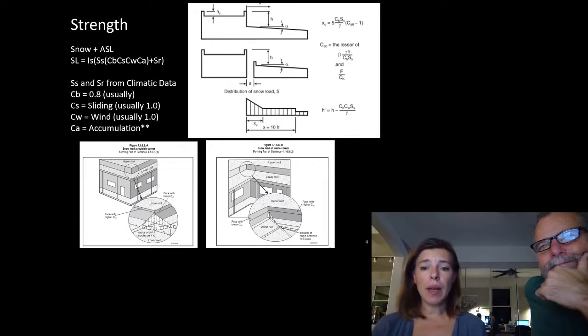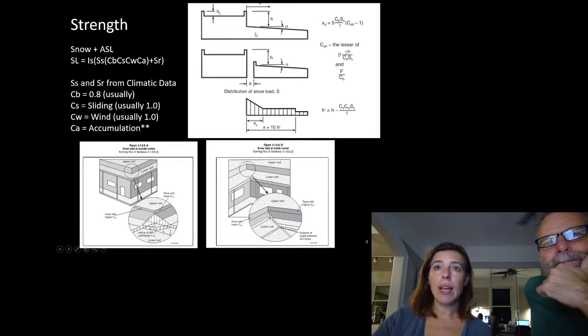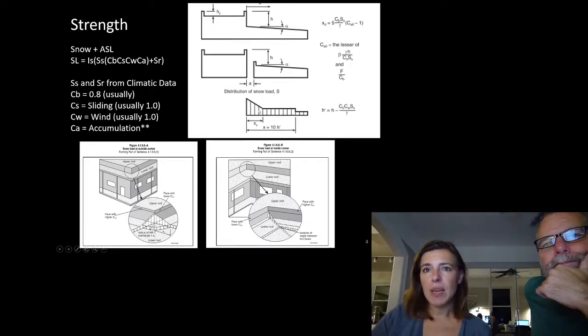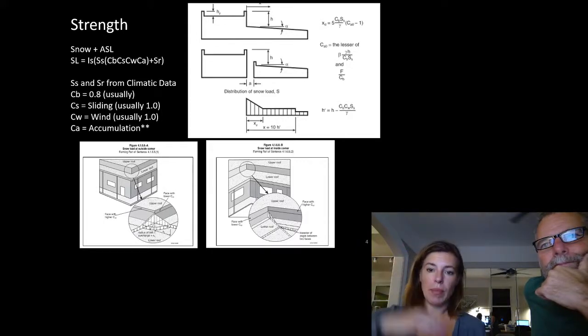But snow load becomes a really governing factor. So you can see that we might have just a small canopy here, and if this is our snow load projection, we might be in this range here. Sometimes what I might do, depending on if the canopy comes out to here, you can see that the snow load decreases quite a bit, and it's worth doing chunks in incremental values of that snow load acting on my model.